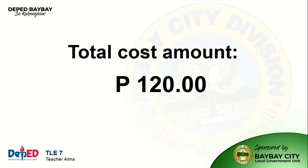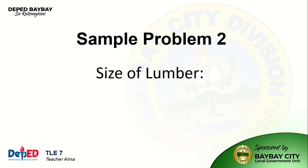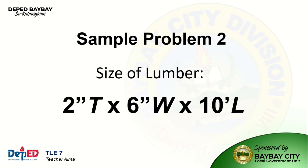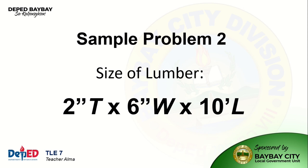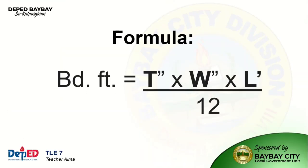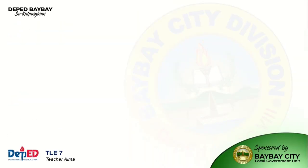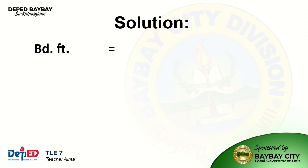Now let's continue to sample problem number 2. If we have a size of lumber of 2 inches thick times 6 inches wide times 10 feet long. As we can see, its length is in feet, so we're going to use formula number 2, which is board feet equals thickness times width times length divided by 12. The solution: board feet is equal to 2 inches thick times 6 inches wide times 10 feet long divided by 12.